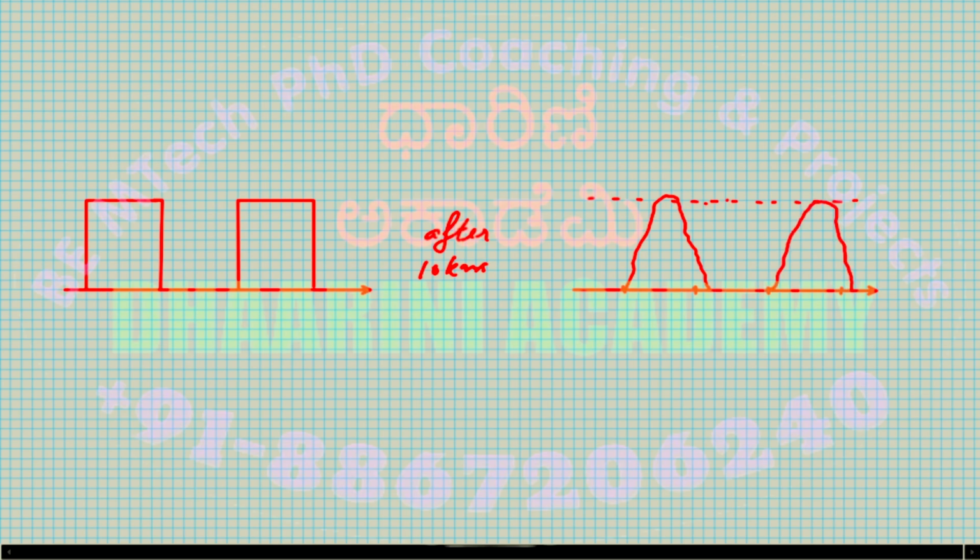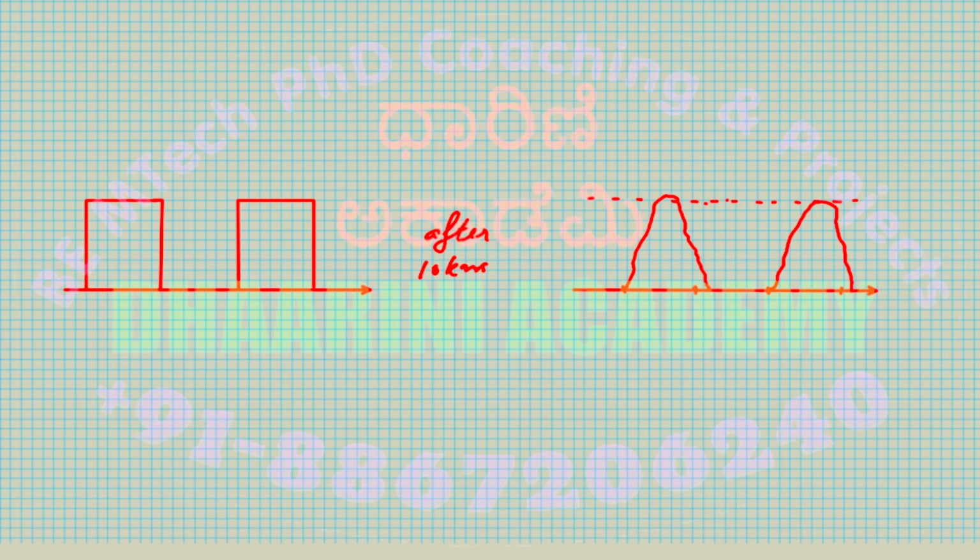right? You see, because of the properties of the channel, obviously. It's nothing, no problem with your transmitter, no problem with the energy or the power you gave to the pulse. It is a property of the channel. Channel is a dispersive medium most of the time, which takes some amount of energy, maybe because your conductor is a resistor. Resistor is a lossy component. We already studied in circuits, right? Whatever energy you give to the resistor, it loses in the form of heat, right? Same thing, attenuation is also another version of talking about the same thing. Perfect, right? So because of that, I get like this.